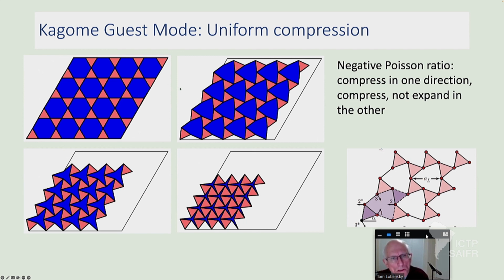I think I've got your question. So the original Kagome lattice doesn't have any of the zero modes and things like that. It is a critical state separating 2 different topology classes. I can either distort this way, and there are lots of other ways I can distort. So, out of this whole zoo of possible structures, there are critical ones where we get these sample-traversing states of self-stress, which change the elasticity.